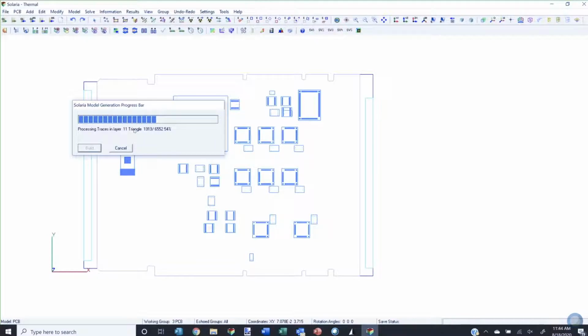And if you notice that in some places on your traces, on your layers, there's splits. There's areas where there's splits in the copper. And this is because one area may be at 3 volts and another area may be at 5 volts. But what a split will do thermally is it makes a thermal disconnect when you're trying to conduct the heat to the edge of the board.